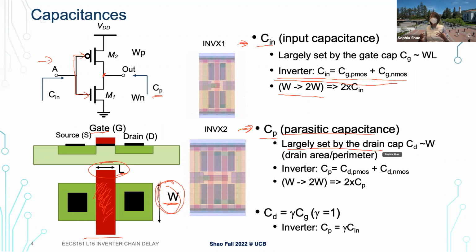So we think about parasitic capacitance. Again, this is largely set by the dimensions of our CMOS circuit. If you have a bigger plate, we have bigger area, we have more charges that we need to charge and discharge. Similarly for the inverter, looking from the outside, it's connected with both the drain terminal of PMOS and the drain terminal of NMOS. Whenever we make the size bigger, it also means we have a bigger parasitic capacitance. That's the overhead we need to consider. We'll also talk about this later, but keep in mind that when we make the dimension bigger, we also increase the parasitic capacitance.